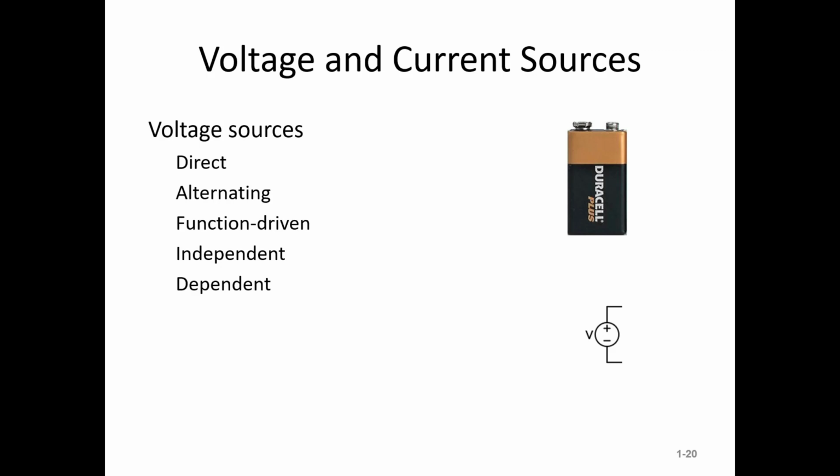Okay, a good example of that, if you've fiddled with cars at all, is an alternator. The charging system in your ICE car, your internal combustion engine car. So there's the bus voltage, which your car tries to maintain at 14 volts. That's a good voltage for charging the battery. That's why they keep it there.